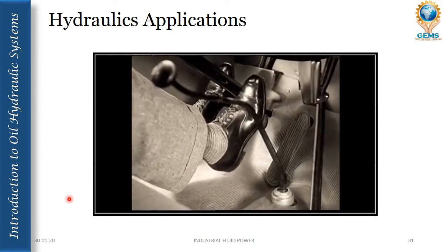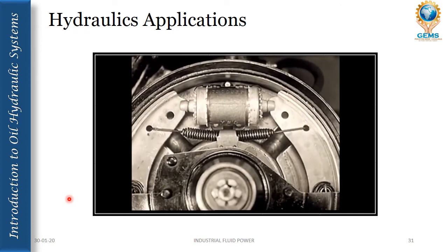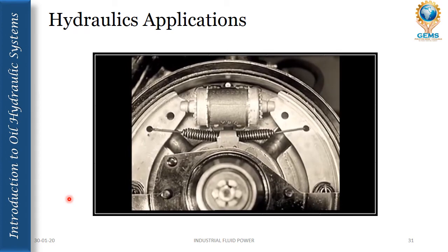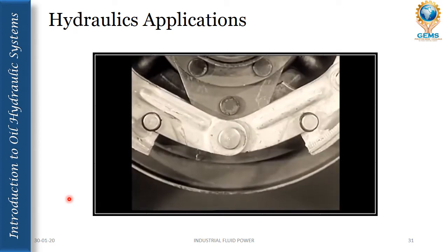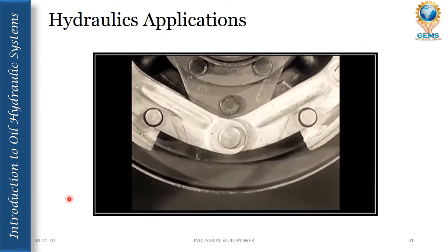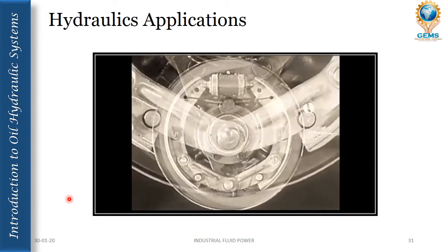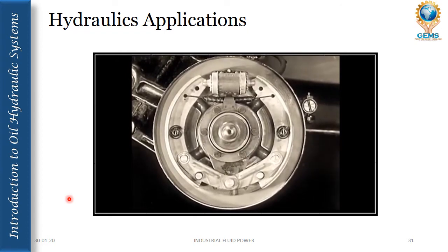Now, when you press down on the brake pedal, each of the 4 power pistons is forced an equal distance against the brake shoes, pressing them uniformly against the brake drum. The shoes are hinged in such a way that the entire lining contacts the drum throughout the life of the car. No grab at the top or bottom. Smooth, even, taking hold by the entire shoe surface.